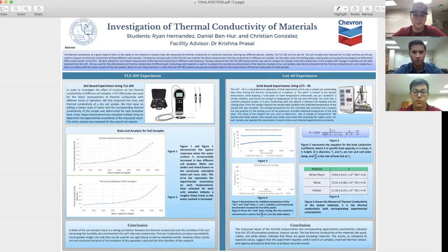We chose to record the temperature every 15 seconds and did this continuously until the hot and cold plates both reached a stabilized temperature. Each trial took at least 45 minutes. That includes the heating and cooling portion. We repeated the experiment for each sample at least 5 trials to reach the stabilized temperature. We slightly heated the cooling plate and allowed it to cool freely at room temperature, and we obtained the cooling curve. We obtained the cooling curve for every trial.